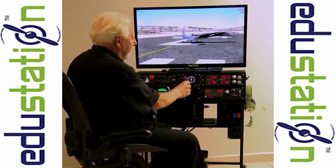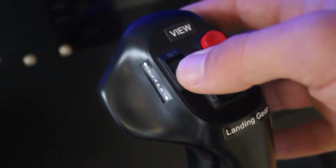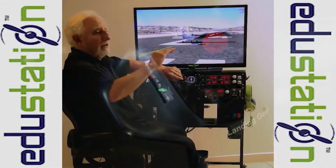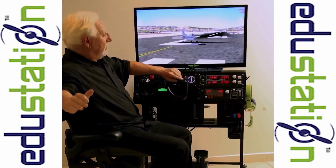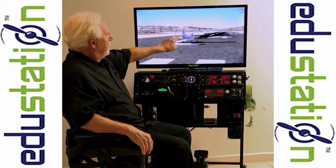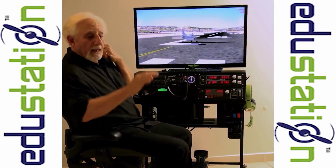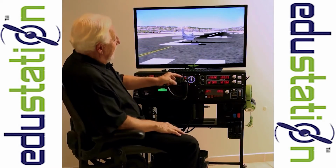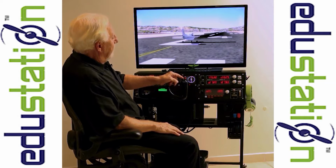The right side of the yoke, the vertical switch, is for the flaps, and the flaps are extended to give us a bigger airfoil and therefore more lift. We use the flaps when we are landing, and there are 3 clicks: 10 degrees, 20 degrees, 30 degrees. And I'm now going to retract them because we do not need the flaps on climb out.